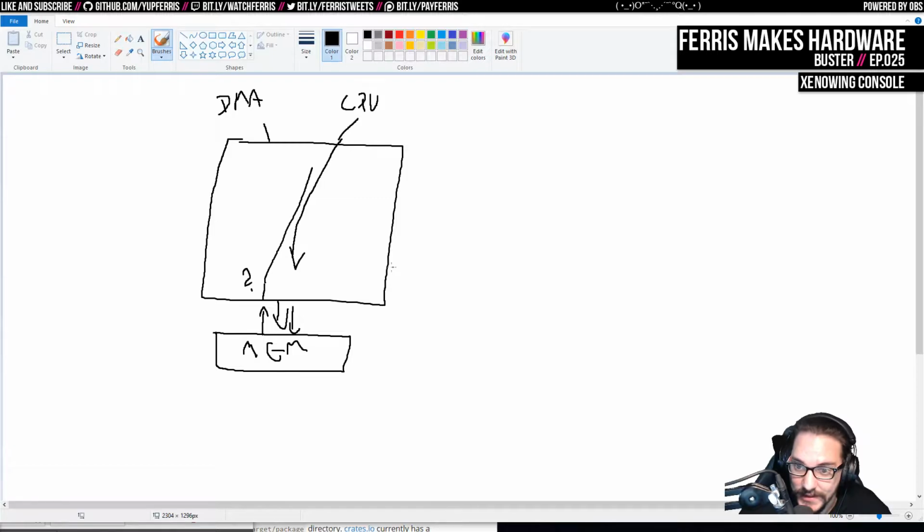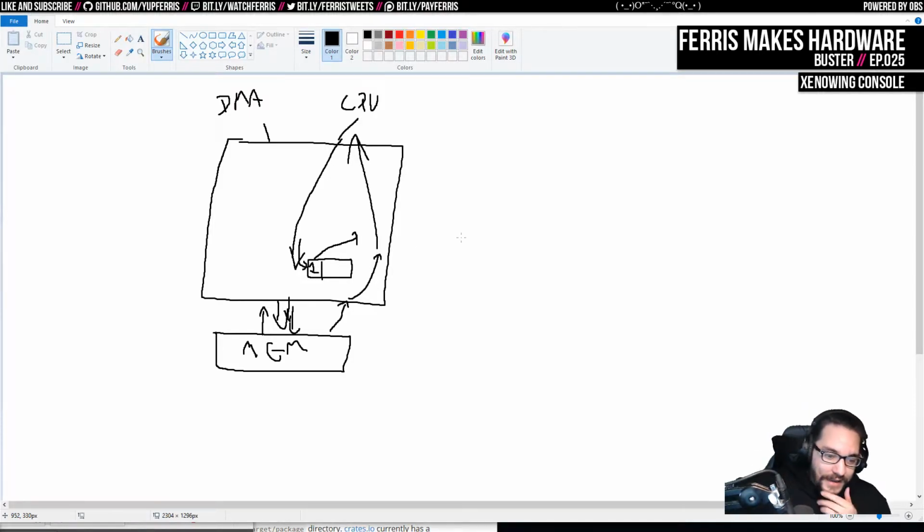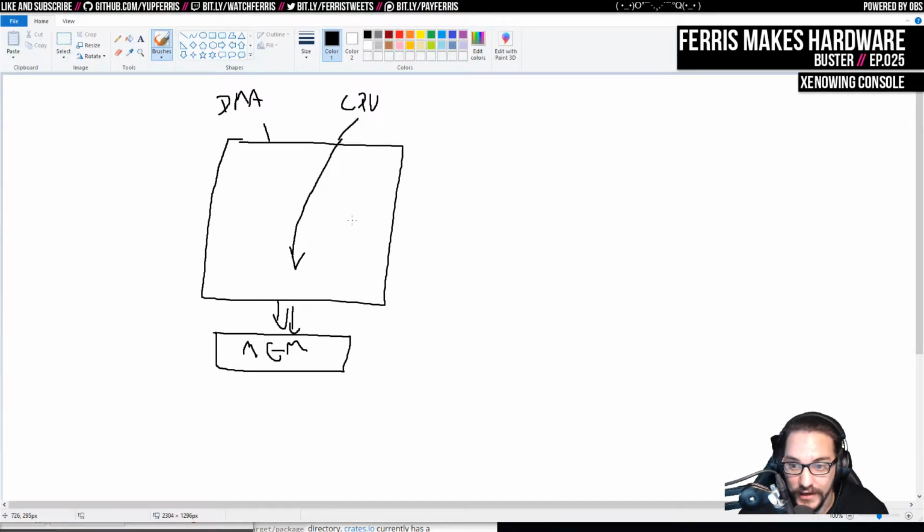And so the way I solved it previously is whenever you would issue a read, you would not only issue a read to the memory, but you also have a little FIFO here, which I'm going to draw like this. So here you issue the data, and then here you issue a 0 or 1 depending on which master it came from. So in this case, it would put a 1 in this FIFO. And then when the data comes back, you pair that data up with the value from the FIFO, and because it's 1 here, you would send this to this one. And that alone is not bad. If you have multiple masters and a single slave, this works just fine. However, if you have multiple slaves, you can run into a weird issue.